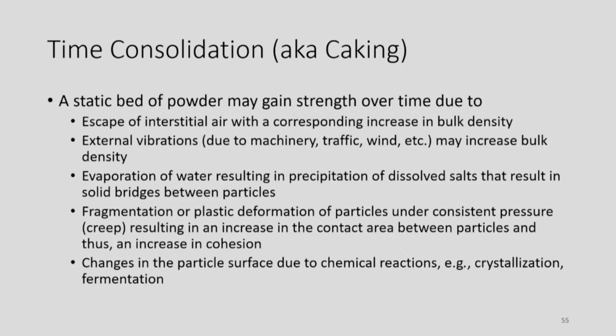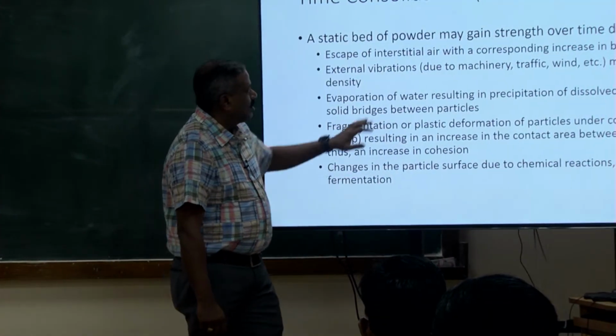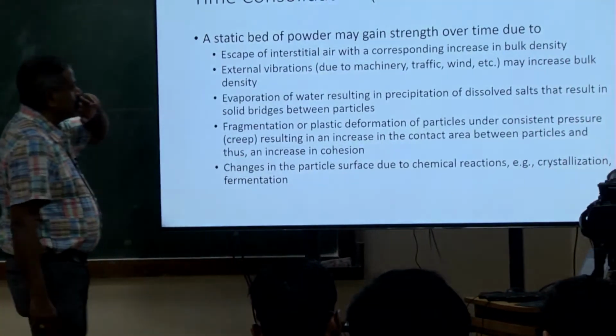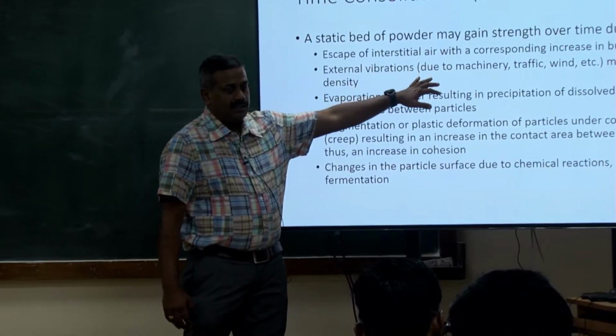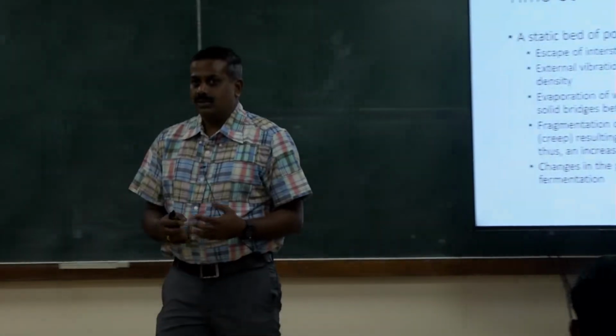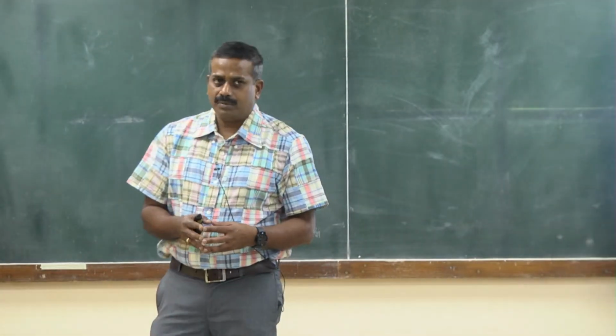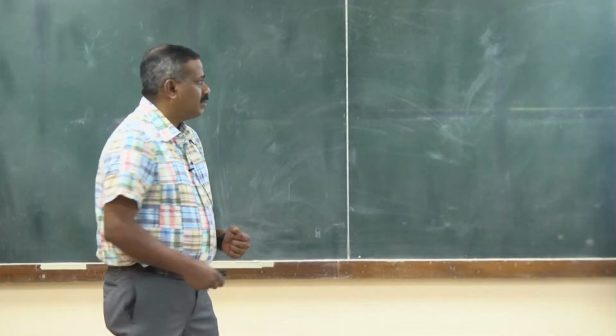And not the eating cake, okay? At least for agriculture students, caking is like agglomeration of powders. So it gains strength, mainly losing permeability and losing interstitial air spaces, and the powders become more cohesive. There could be some moisture absorption and adsorption that leads to bridging between particles, and then they can cake too.